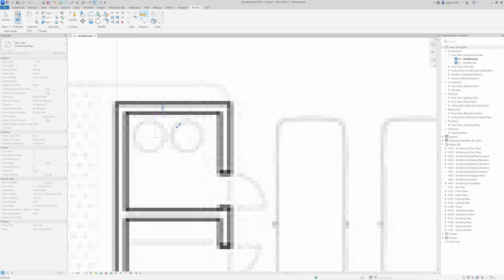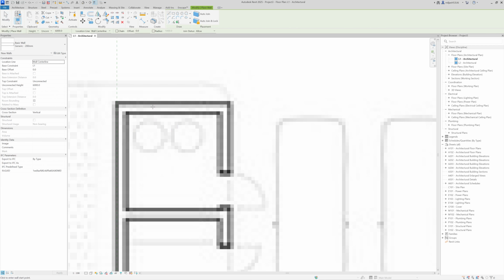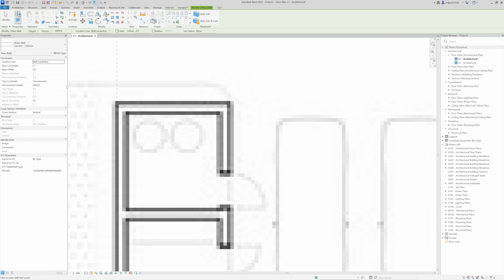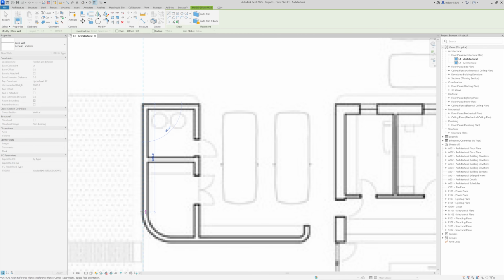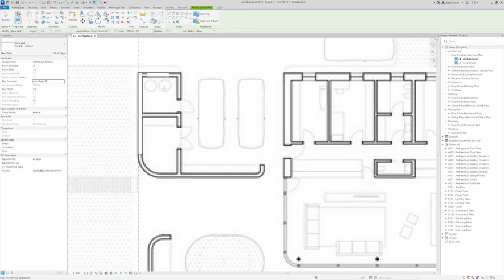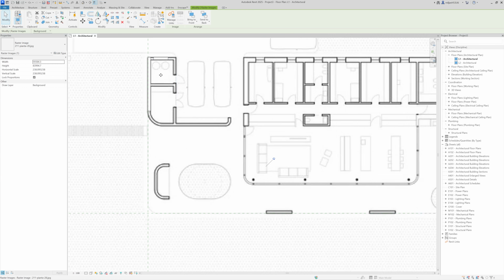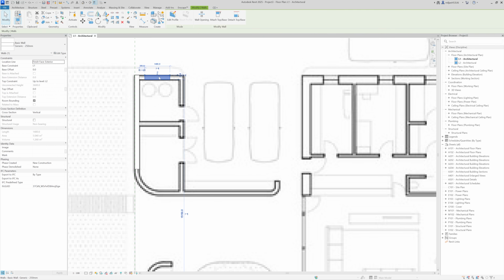So this wall is around 250 and I'm going to create a wall which is 250. We'll place it on the second level, and what is very important, I'm going to take this Finish Face Exterior for location line. And because I'm placing it from the reference plane, I would like to have this as a clear number. See? And then I can continue placing my walls.